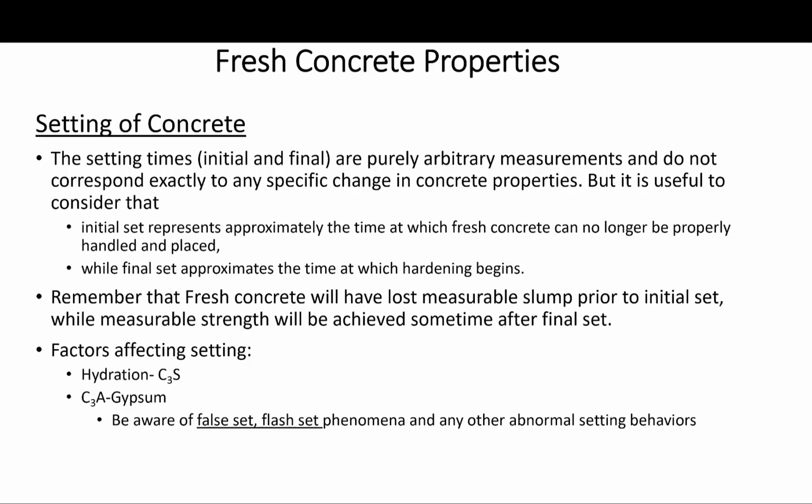Okay? So setting is controlled primarily by the hydration of C3S. And the period of fluidity corresponds to the induction period, which is stage 2 we discussed previously, if you refer back to the heat of hydration curve.